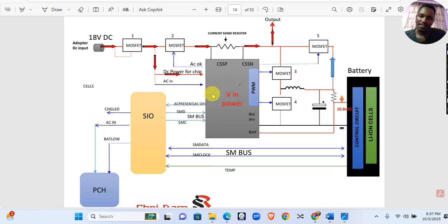Why? Because this IC should have a line which controls this MOSFET. In fact, each and every MOSFET has an IC responsible for it. So when you suspect your MOSFET is faulty, you should still consider checking the IC responsible for that power supply, right?